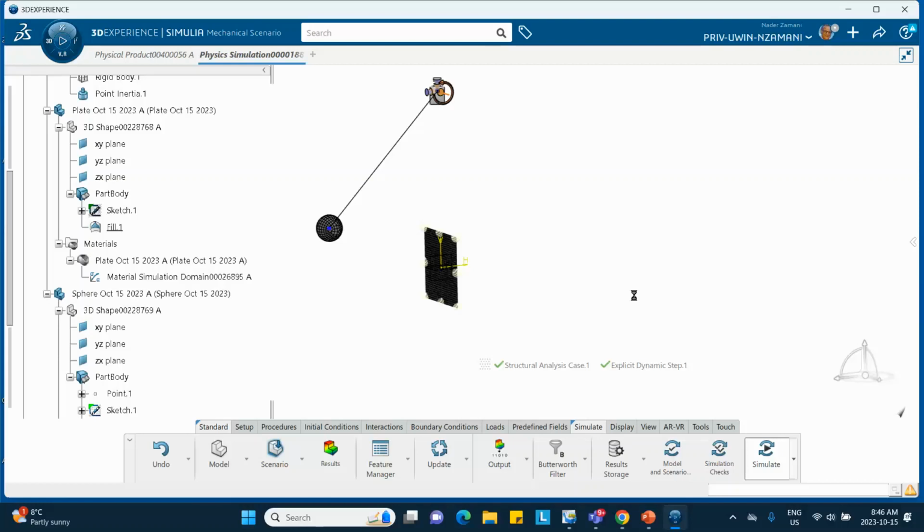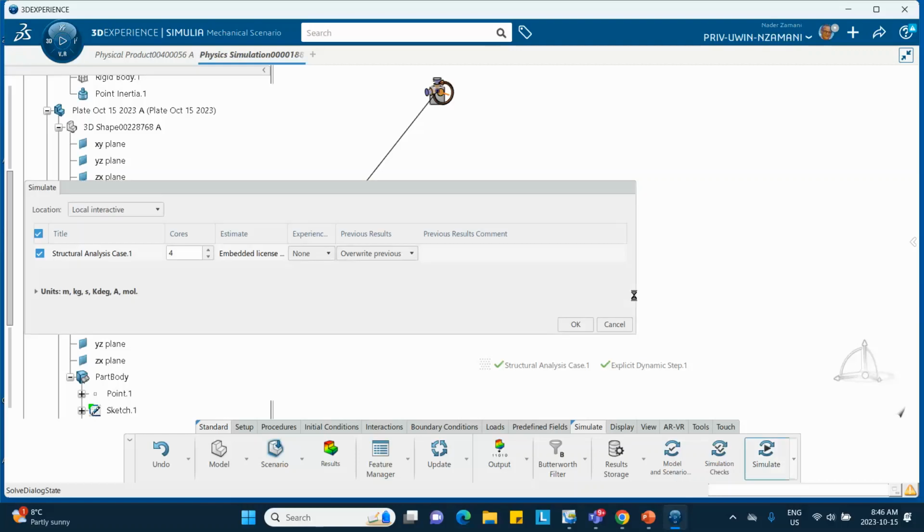I won't run it until the very end, but I will stop it and look at the results. When you stop it and look at the results, obviously you didn't finish the run. ABAQUS users call this a restart, but I'm not interested in it. I just want to see what is the effect of removing that damage evolution parameter.